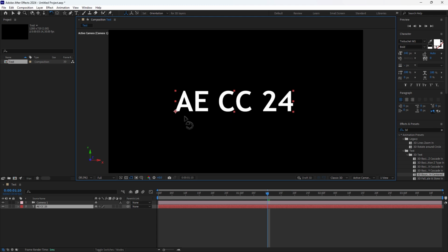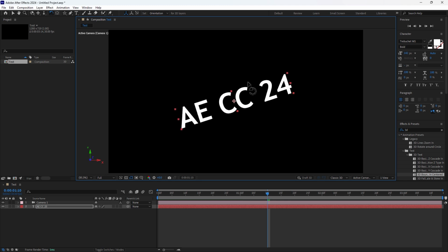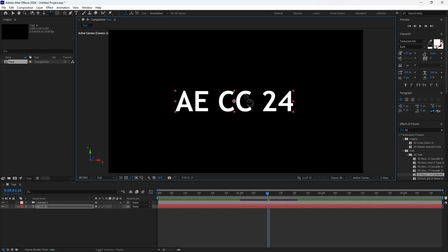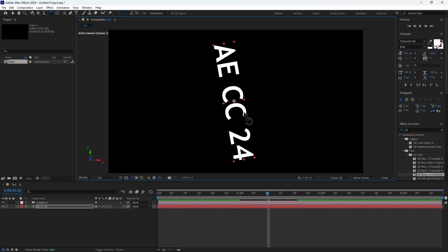So if you need to change the anchor point position from there to center, or move it to the right corner, press Y or go to Tools, select the anchor point tool and move it to the center of the title, and select rotate like this. Hold Shift on the keyboard, rotate, select again, rotate, hold Shift, 5 degrees.